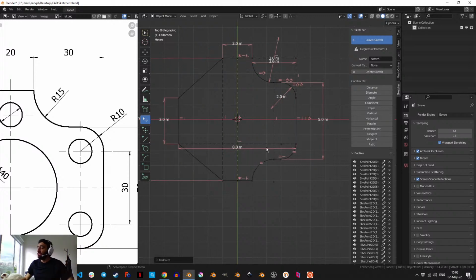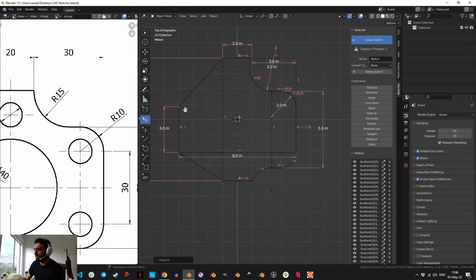There you go. So this was the key. So now our drawing is completely centered, and we are down to only 1 degree of freedom. So there's only one thing that I can mess up by hand, and is not defined by a parameter. Let's find it. I think I got it now.